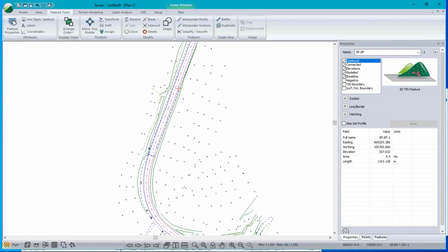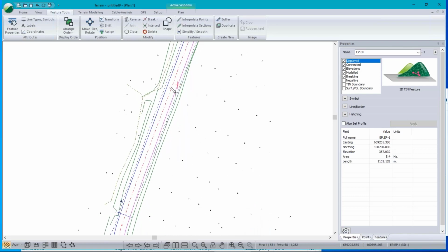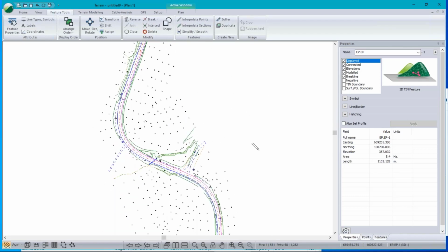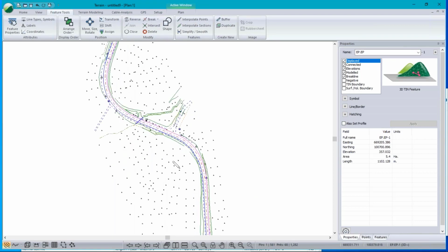Just double checking that I covered all the fixes. We covered an out of order break line, and joining points using a polygon. Oh, bad elevations, right. Again, with this one, we had a couple of bad XY coordinates. Very often you get bad elevations. Let's use this model to demonstrate that.